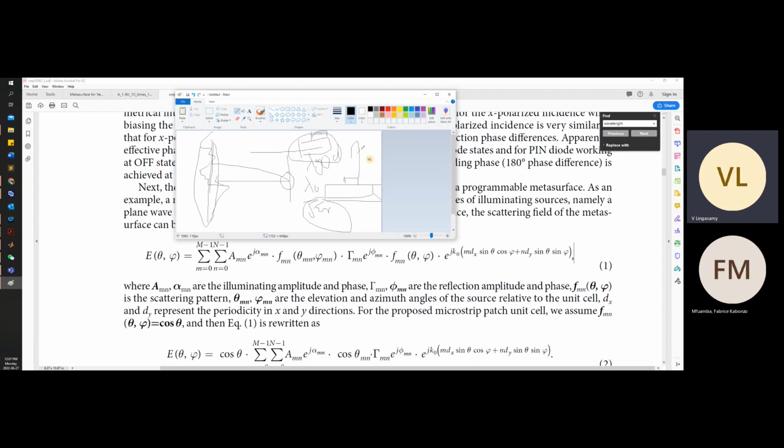The moment the wave enters the patch, it enters a complex medium, basically an artificial dielectric. A substrate alone will behave in one fashion, but if it is printed with patches of different shapes, it will behave in a different manner, and the effective dielectric constant will become different. The wave is getting inside, and if you have a ground plane, it gets reflected. So what is happening?